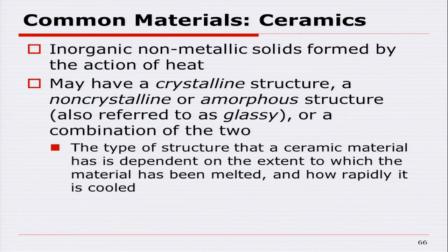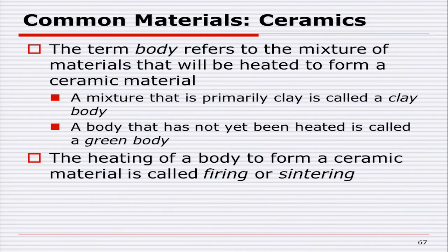The next category of materials is ceramics, and those are inorganic, not organic, inorganic, in this particular case, non-metallic solids formed by the action of heat. And what we're typically doing again is taking really soil minerals, typically clay minerals in this respect, and packing them together just like we did with our other sintered products, forming them into some kind of a shape and heating them up.